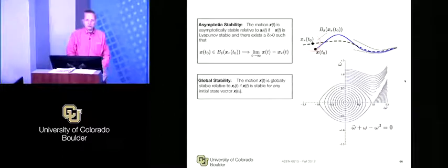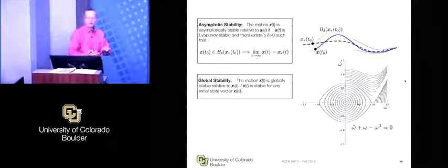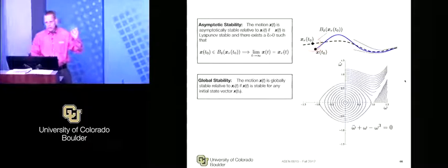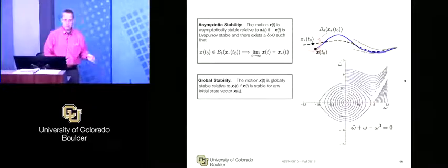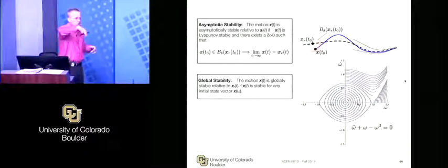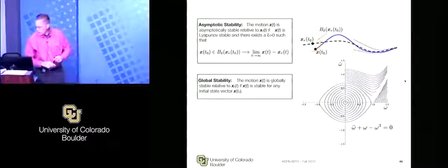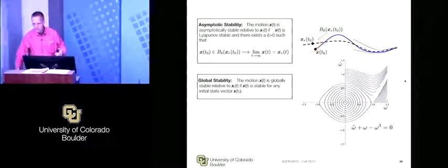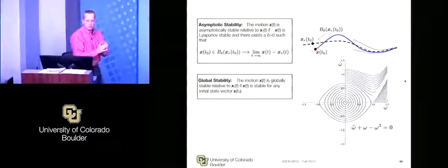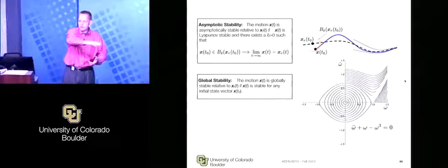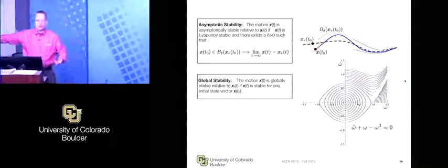So with nonlinear control, we have Lagrange stability, Lyapunov stability, asymptotic stability, and each one of those is global or local. And the other thing is exponential stability, which I don't cover much in class, but you have to look at, you know, there's some decaying asymptotic function. And that's one that you have to do as well. That'll guarantee how fast you perform. Asymptotic stability just means you will get to 0. You may get close to 0 very quickly, and then it may take eons, literally, to converge.